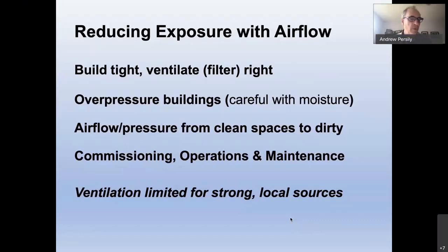And then the last point here is that ventilation will only get you so far if you have a strong local source. If you have an open can of paint in the room, you're not going to solve that with ventilation. If you have an unmasked, ill, coughing person in the room, you're not going to solve that with ventilation. You've got to deal with the source, either ideally get it out of the space or do something else.